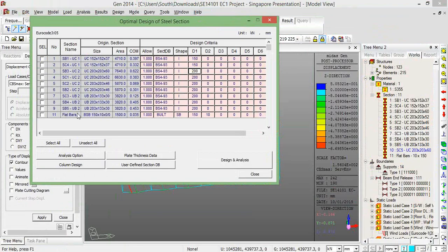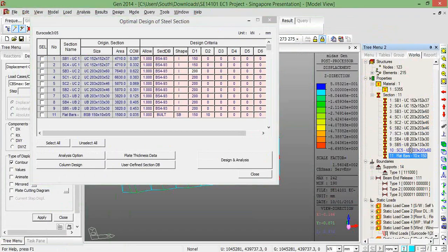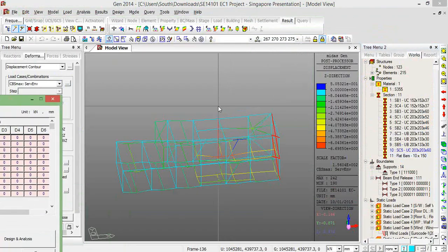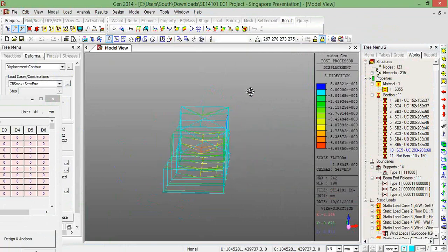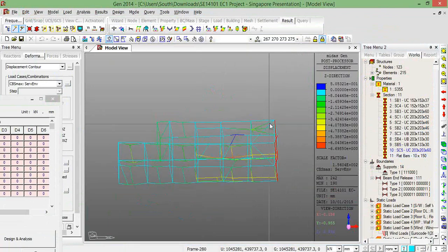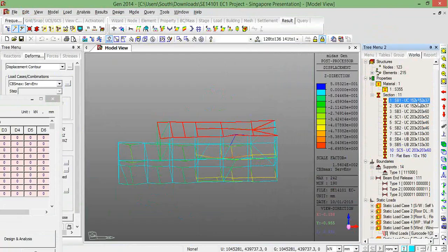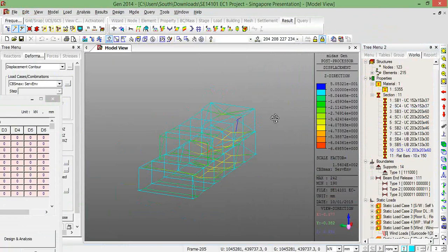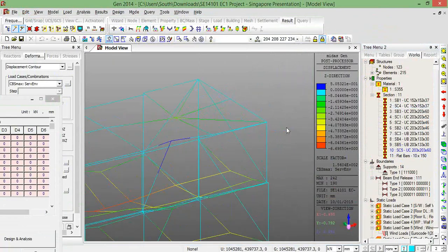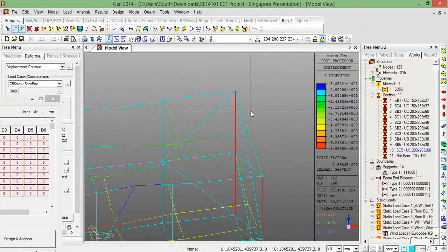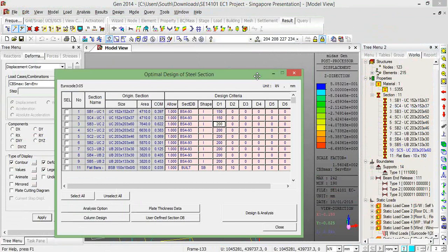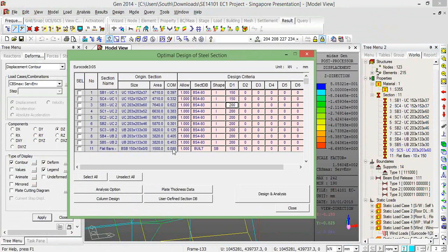As goes for this case where we've got the flat bars. They have been brought in just to provide additional stiffness to that rear frame, just so it doesn't sway too much whilst we're butting against the neighbouring hotel, and particularly because we've reduced the steel section of that rear frame to allow for the stairs to come up, so we had to reintroduce some lateral stiffness from another method. So the steel code check says that those have been overly designed.